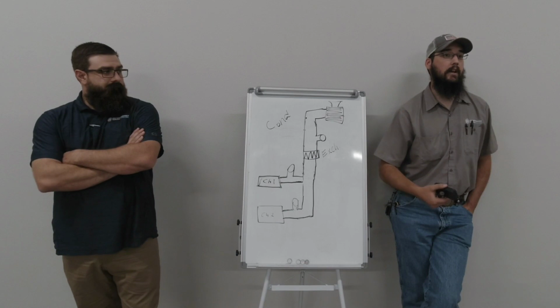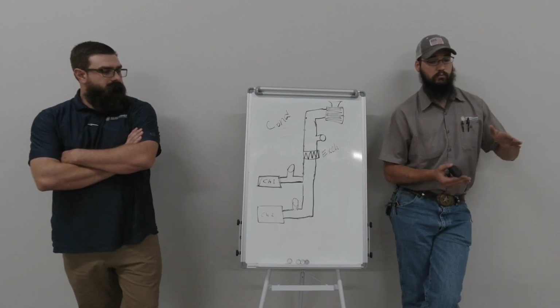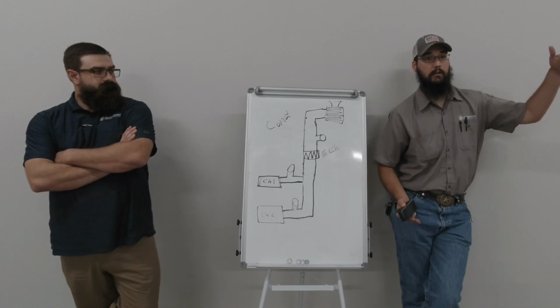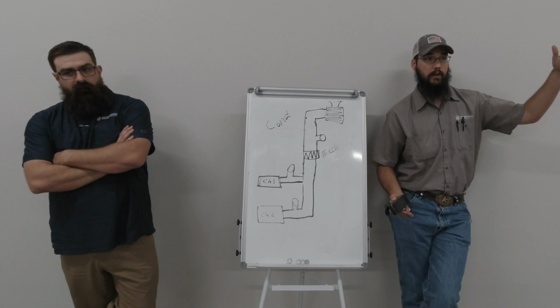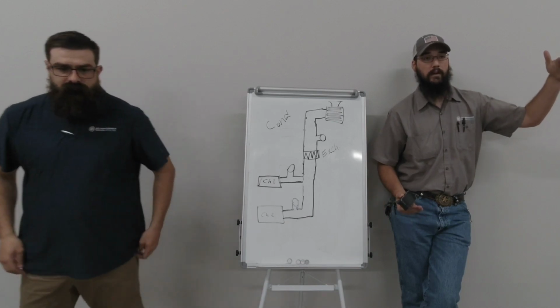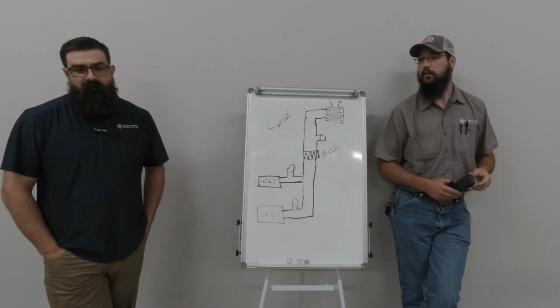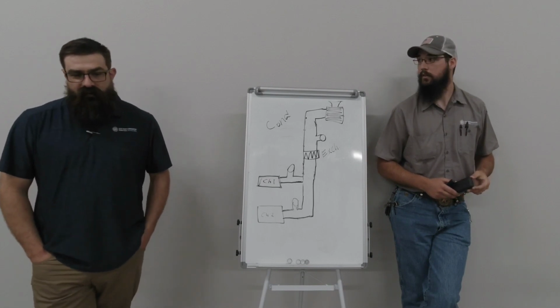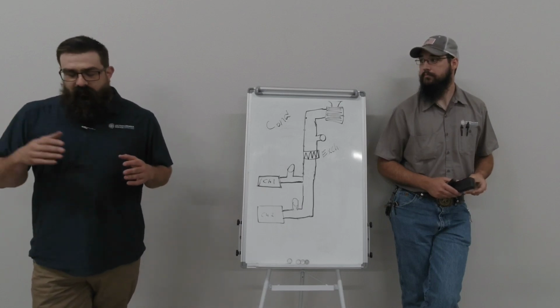That would be an immediate indicator of a flow issue to me, because I have a whole lot of differential between the pressures and the temperatures. If I increase my flow, my expectation is that differential would decrease. That's one thing to remember: flow and temperature are directly related, not pressure.